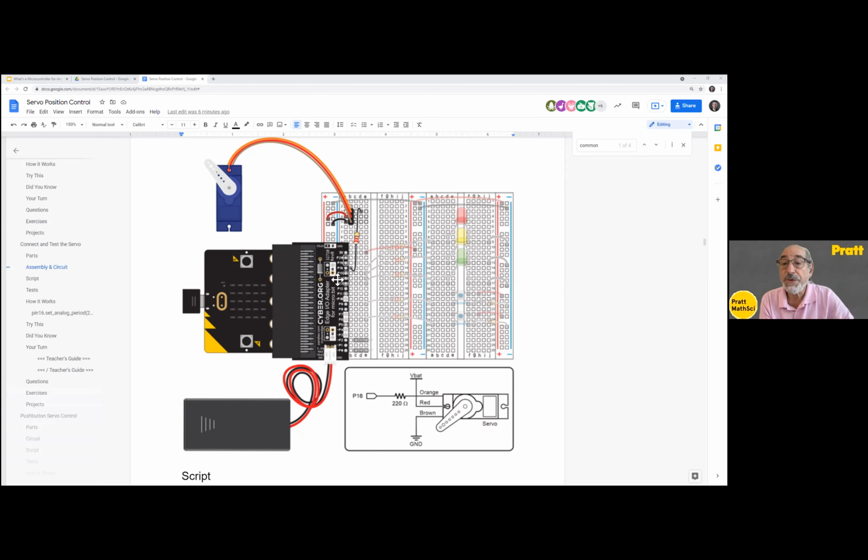The other thing I would point out is that in real life, I've gone away from using batteries, and we use either the battery adapters, which are usually like the 5-volt phone adapters, and if necessary, we put a voltage regulator on the other end to make it easier.